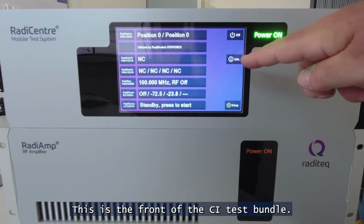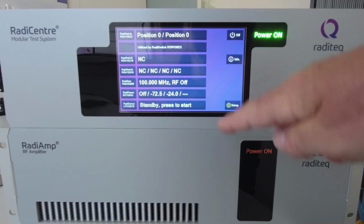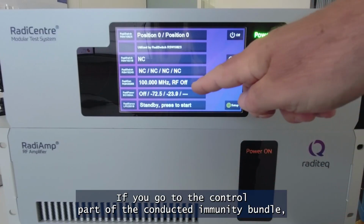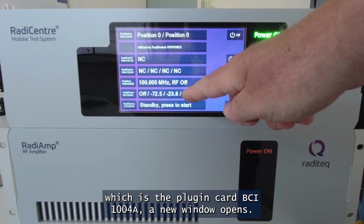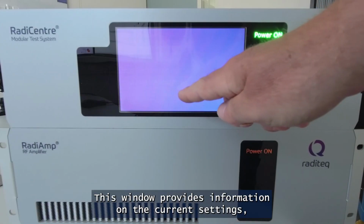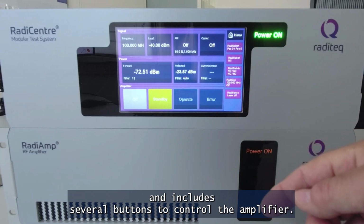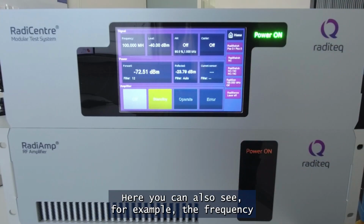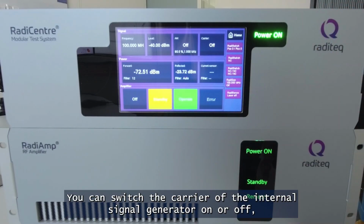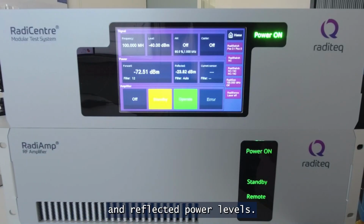This is the front of the CI test bundle. On the top, you can see the Radicenter, and below it the amplifier. If you go to the control part of the Conducted Immunity Bundle, which is the plug-in card BCI1004A, a new window opens. This window provides information on the current settings and includes several buttons to control the amplifier. Here you can also see, for example, the frequency, which you can change, as well as the actual modulation. You can switch the carrier of the internal signal generator on or off. And you can read the actual measured forward and reflected power levels.